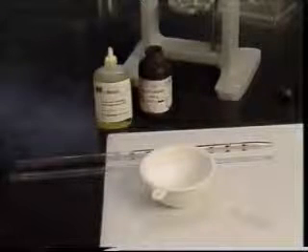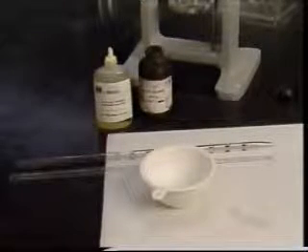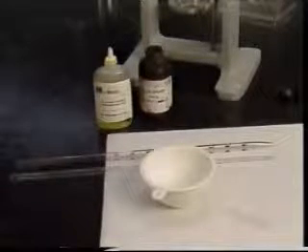Any physical description of the filter cake is also included, such as soft, firm, flexible, brittle, and so on. One of the most common tests performed on the filtrate is the chloride test, used for checking salt contamination and for determining concentrations in salt muds.